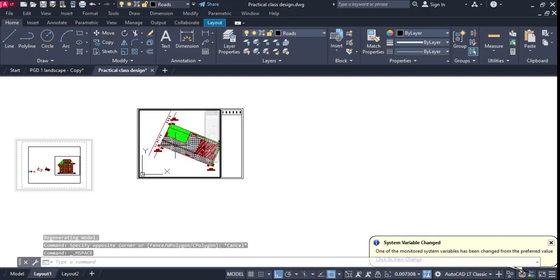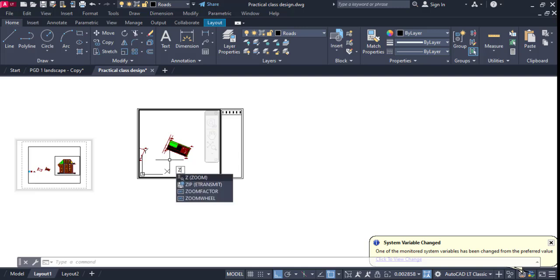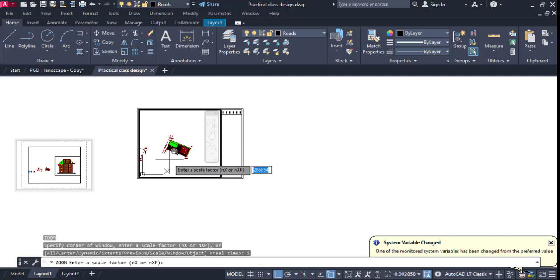And let's say I want to print my, oh god, my site plan. So I want to scale this to a scale I want. The way to do it is this. Now observe what I want to do. I'll click on Z, letter Z for zebra. Okay, enter. S for snake, enter.